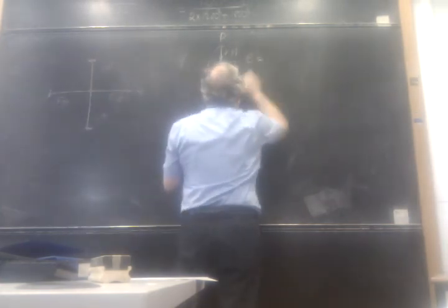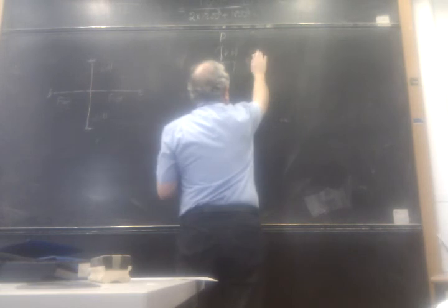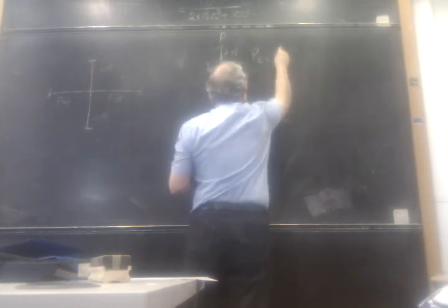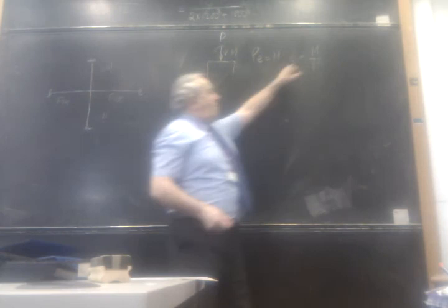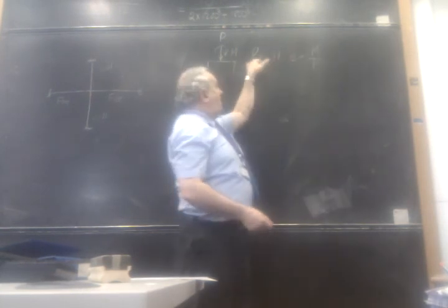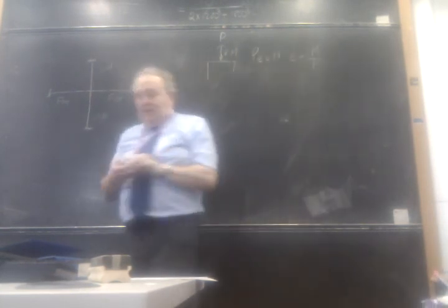The eccentricity is given by, perhaps easier to remember it, P times E is equal to M. So eccentricity is M over P. I think sometimes in the heat of exams and elsewhere, one can get those mixed up. So it's much better to think where it comes from. That way, less to learn.